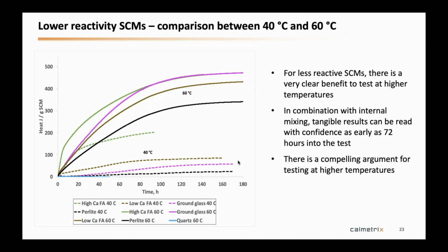There's the distribution of particles, there's a packing effect, there are interactions with some other components in the cement. And you should even test it with the cement and admixtures, because an SCM can react a certain way just with pure calcium hydroxide and some alkali. It will react slightly differently with certain cements because the chemistry varies a little bit, and depending also on the particle size distributions and many other factors. And it will vary even more if you have admixtures in there. The chemistry gets all changed when you have admixtures in there.